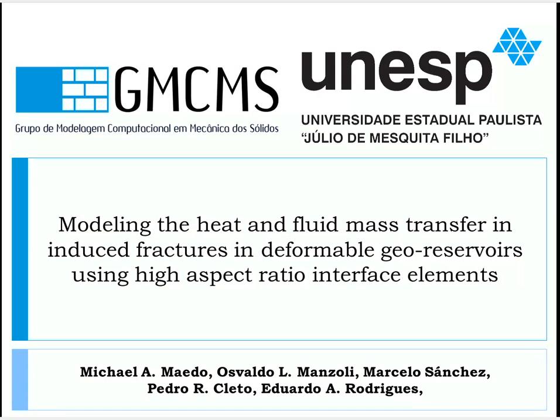Today, I will talk about modeling the heat and fluid mass transfer in induced fractures in deformable geo-reservoirs using high aspect ratio interface elements. And why is this topic so important? Well, because the extraction of natural resources from geo-reservoirs requires advanced techniques to increase the productivity of the reservoir and at the same time prevent environmental problems.